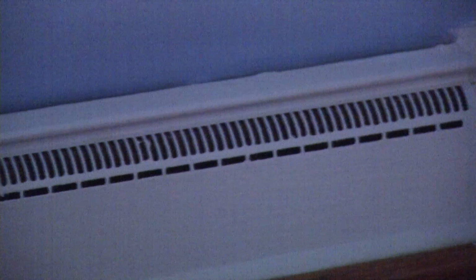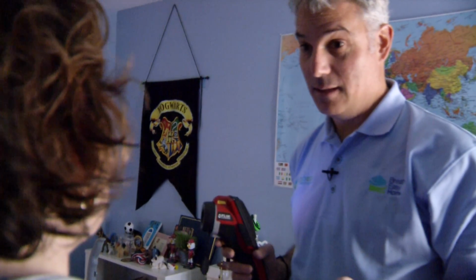Another reason why this room may be so cold in the winter and hot in the summer is because of the ducts. This supply register here on the wall that heats and cools this room is the furthest one from your heating and cooling equipment way down in the basement. Right. So it has a long, long way to go. And if you have leaky ducts or ducts with lots of bends in them, or it's not properly configured, that can all really affect how much air comes out of there and how warm or cool that air is. So we'll take a look at that too.